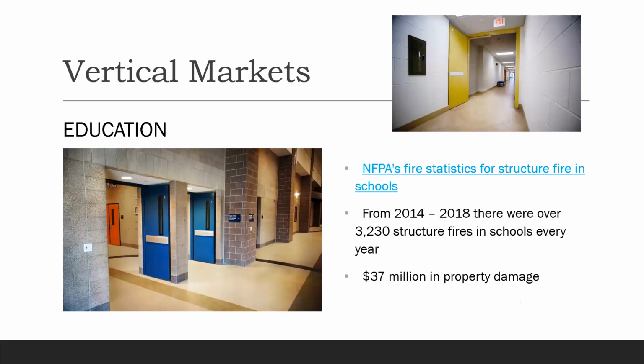Now, most school fires occur between 8 a.m. and 4 p.m., of course. That's when the students and staff are there, right? Often means of egress doors and stairwell doors are required in schools for protection. And so there is hardware that's made for these high traffic, high abuse situations. You know how students are always running, kicking the doors open, karate chopping the doors open. If they're held open unless triggered by the smoke alarm, they will take less abuse.